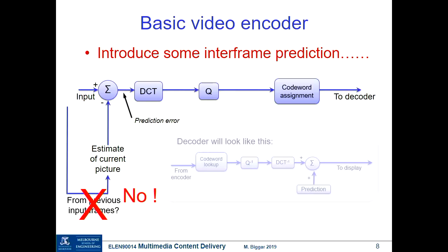That's Huffman coding, and this is undoing the Huffman coding. So we can say that from that point to that point is transparent, assuming there are no transmission errors. I mean, does the Huffman coding do prediction too? No, the Huffman coding simply assigns code words. If you have a series of symbols that you want to represent, such as quantization levels, the Huffman coder will assign a variable length code depending on the probability of the symbols. But Huffman coding by itself will not do predictive coding.